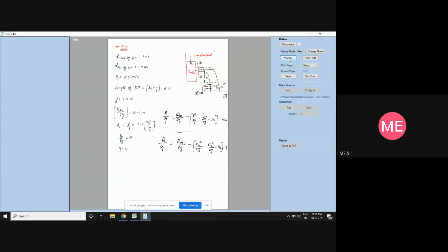The above formula converts this way because while deriving, we took sections 1 and 2, but in the problem we have taken sections 2 and 3 for the draft tube. Wherever 1 is there, you substitute 2, wherever 2 is there, substitute 3.